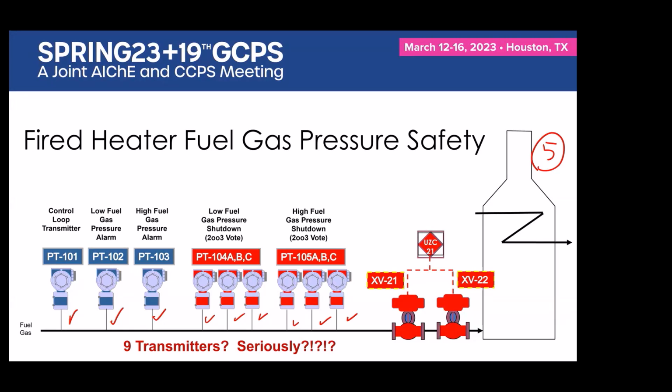Well, we're putting all of these extra pieces of equipment in because we need each piece of our LOPA to be separate. Because the bottom line is LOPA's math can't handle a shared component, but fault tree analysis can. That's why sometimes you might want to switch over to fault tree analysis to look at some of these scenarios.